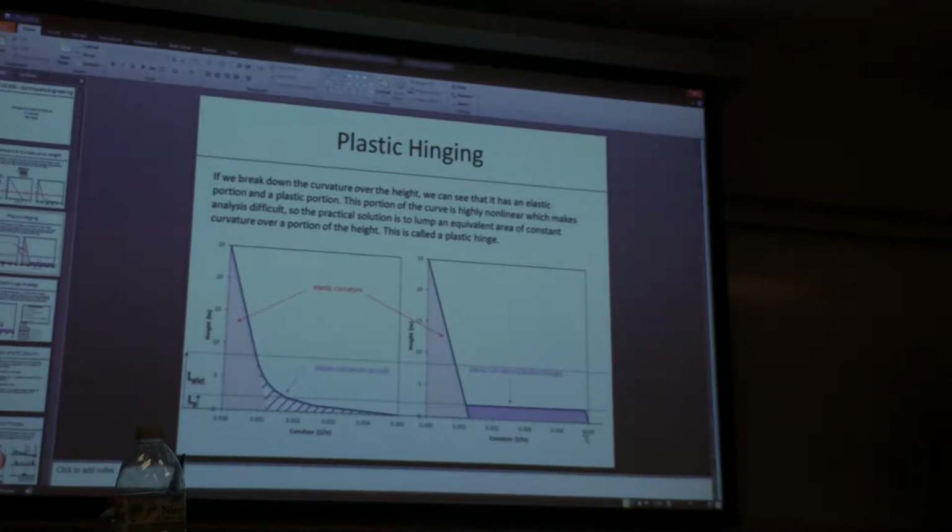You can say, what's the displacement capacity of this frame? What force is required to push this frame over? And then obviously you can correlate that to your design stuff. We talked about the code design. You can compare with your design forces as you're pushing this over, what are the resultant curvatures and rotations in your column, and are they satisfactory, right? You can check to see, did this frame exceed its plastic rotation capacity? And if it did, obviously you would go back and change your design. If it doesn't, well then you verified your design is working correctly. That's stuff that we're going to do next.